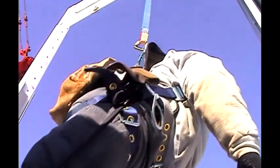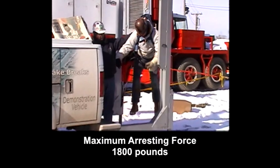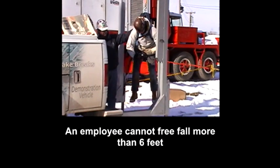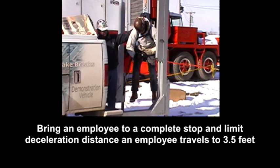Personal fall arrest systems must limit maximum arresting force on an employee to 1,800 pounds. Be rigged so that an employee cannot free fall more than 6 feet, nor contact any lower level. Bring an employee to a complete stop and limit deceleration distance an employee travels to 3.5 feet.